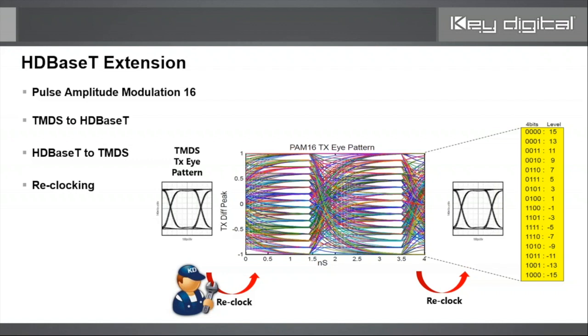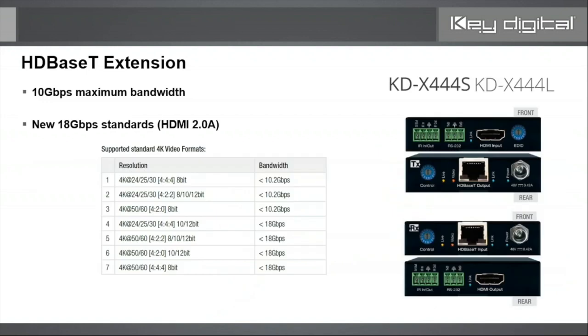And the beautiful thing was, because we had already had TMDS reclocking as part of our full buffer technology suite, we were already doing the clock stretching, excuse me, the reclocking. And so when folks called and said, hey, what are you doing about clock stretching? We were not experiencing that problem because our extenders like our Cat HD 300 Lite, Cat HD 500 Pros, they were already reclocking on the front end. So the folks working with Key Digital's products were not experiencing that problem, and it was a very large problem in the industry for a while.